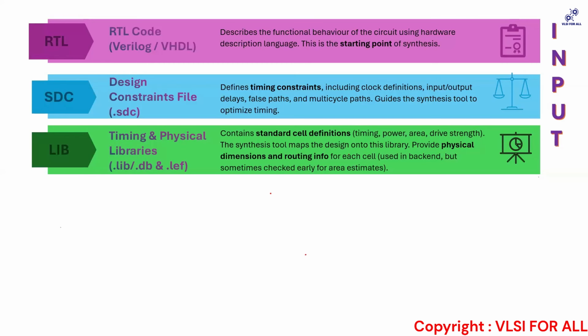So depending upon these constraints, the tool, like your Design Compiler or your Fusion Compiler, selects which flavor or which form of gate I have to use. It can be based upon various drive strengths. There are also different VT flavors of design available, if I want my design to be low leakage or very fast. Depending upon this, it will go into different libraries and select it.